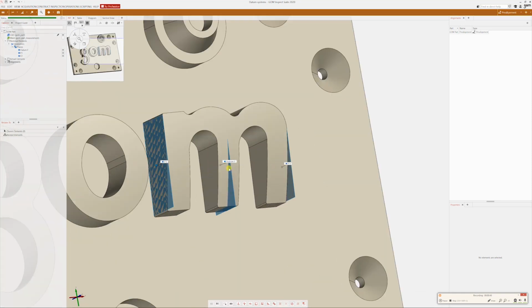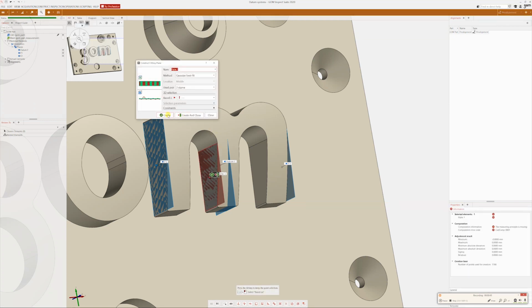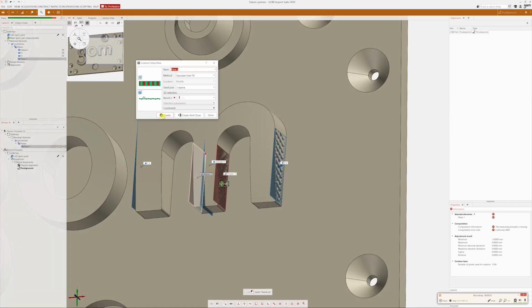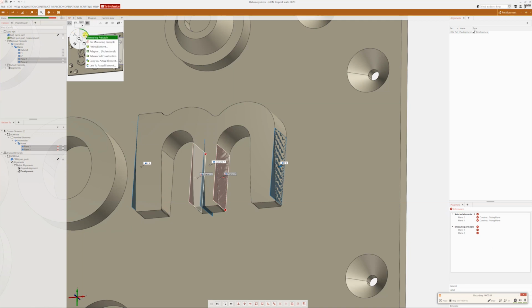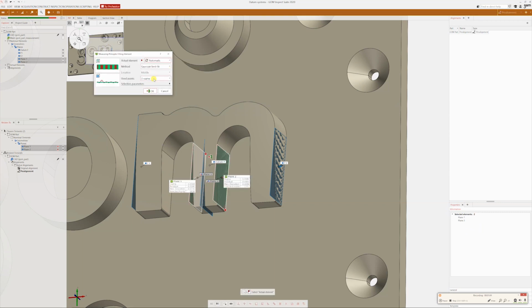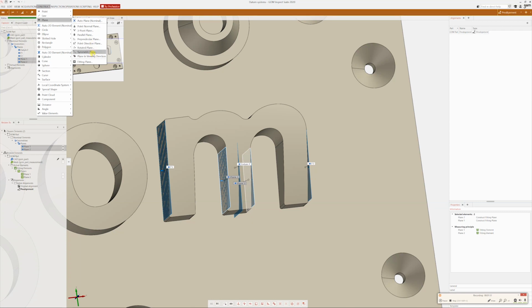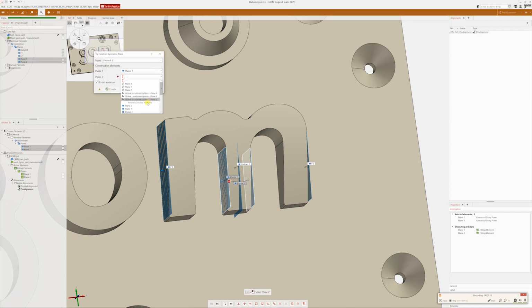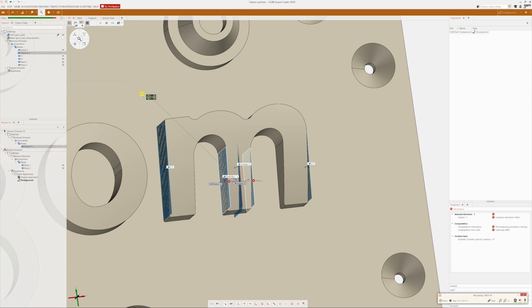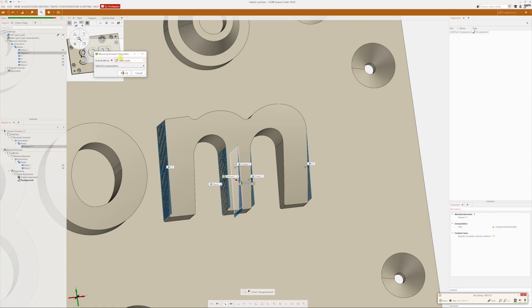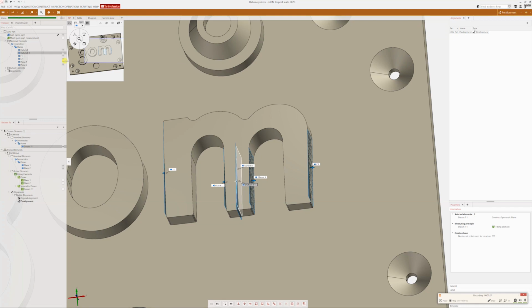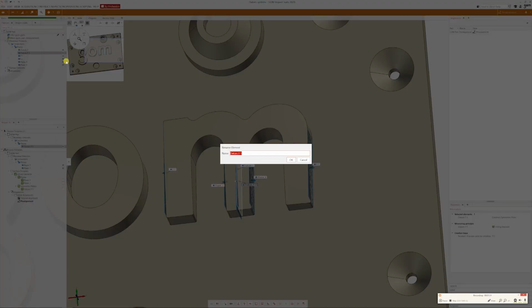Okay, so we make again a fitting plane right here, and another one right here. Okay, we now set the measuring principle as fitting element, best fit 3 sigma. Okay, good. And now we can construct again a median plane, a symmetric plane, from plane 1 and plane 2. Create and close. Fitting element, automatic. Let's rename this as symmetry plane 1.